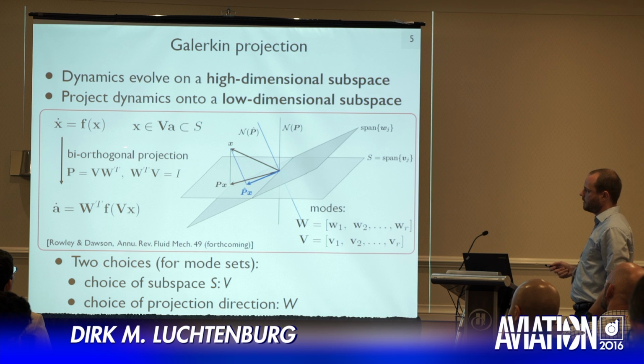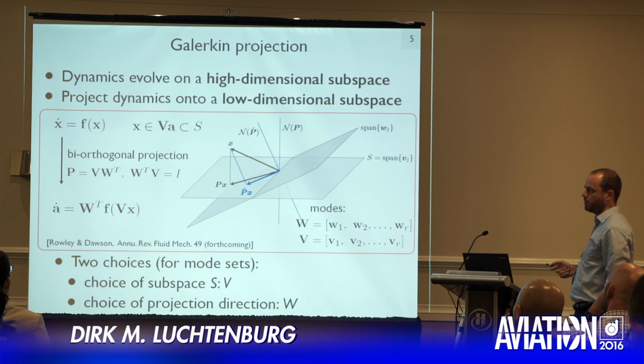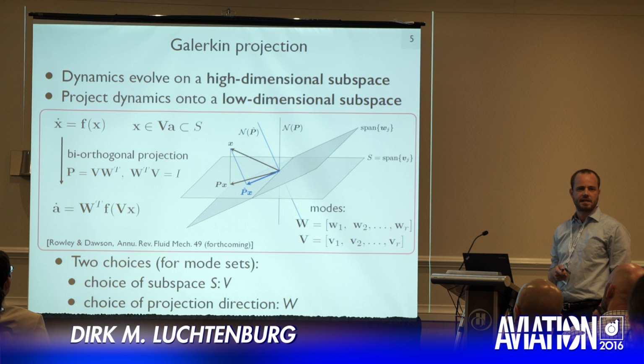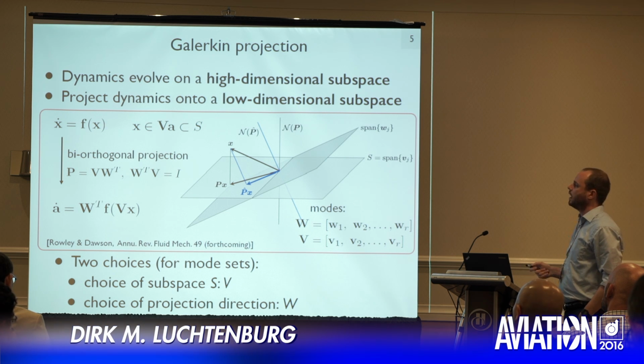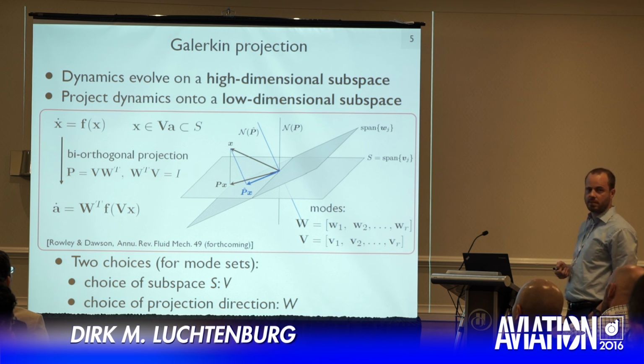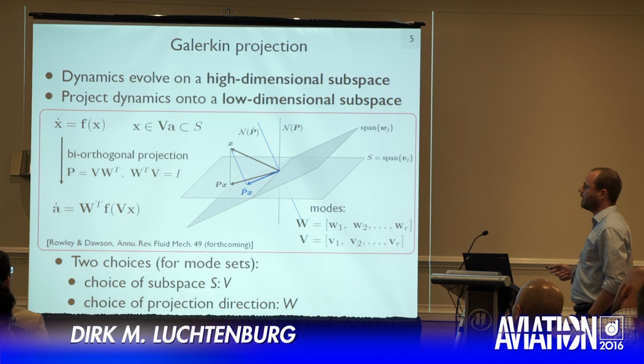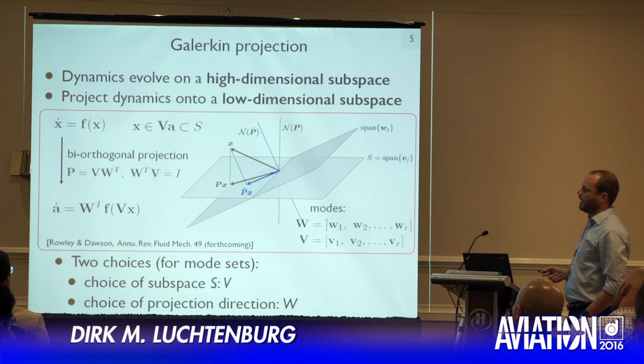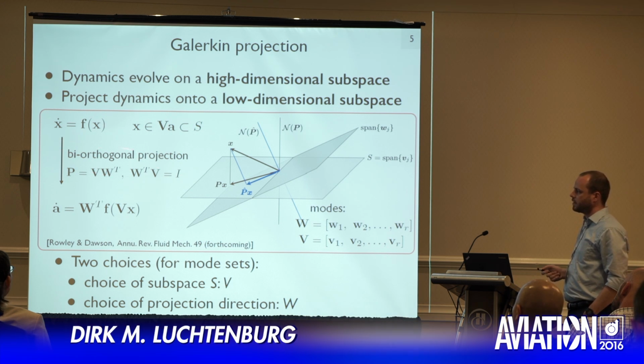Imagine that our dynamics are governed by this differential equation, where x is the state. This formulation assumes that you have discretized, say, your Navier-Stokes equations, so x represents, say, the velocity. What we do is project these equations with a biorthogonal projection.